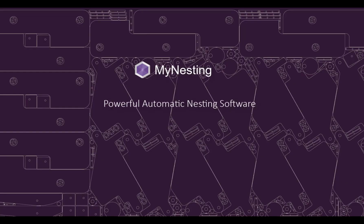It is useful to export your nest multiple times using different settings in order to find the perfect combination. After spending your credit in MyNesting, you can export as many times as you wish within the same session. These export settings are the same for MyNesting and NestFab.